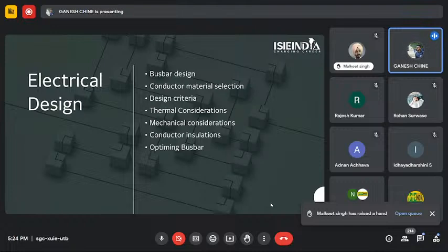If the material has low electrical resistance, the heat generation in that bus bar is less, and the temperature does not rise. It also requires high mechanical strength in tension, compression and shear, and when the material has resistance, the temperature is raised.